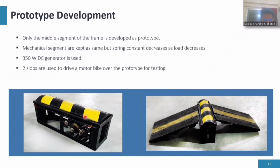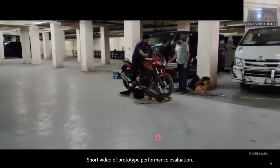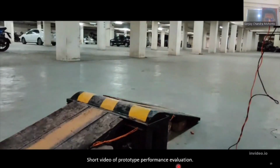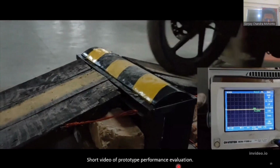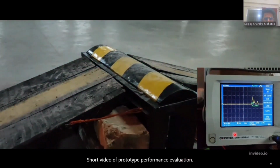We have developed a prototype for only the middle segment of the main frame. We have used a DC generator of 350 watt, 3000 RPM due to unavailability of the expected product. Two sloped wires are attached to pass a motorbike over the prototype. So here is a short video of prototype testing. Here you can see we measure voltage using an oscilloscope.